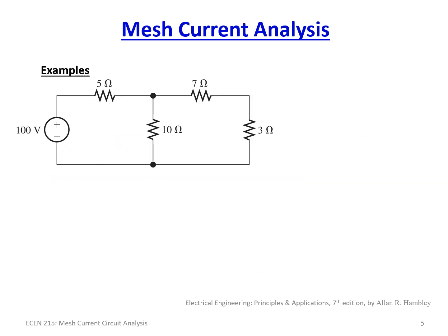So with this problem here, we're going to do the exact same thing. We're going to write 2 equations. We got I1 and I2, and we simply want to write the equations. So let's do that. For mesh current number 1, this is equation 1. I've written 1 here. This is equation 1 dealing with loop 1.